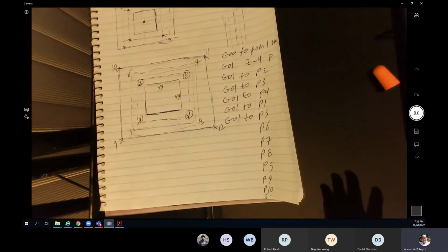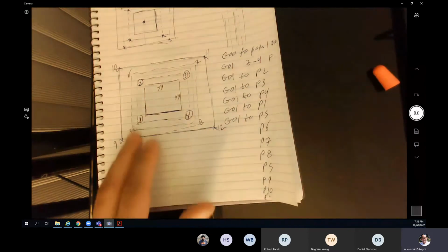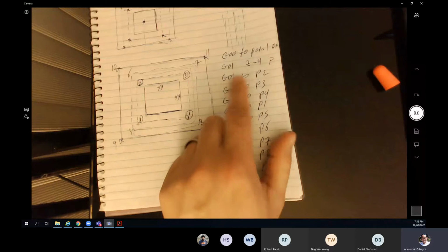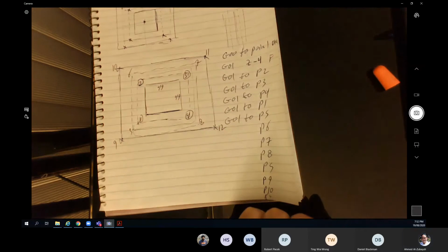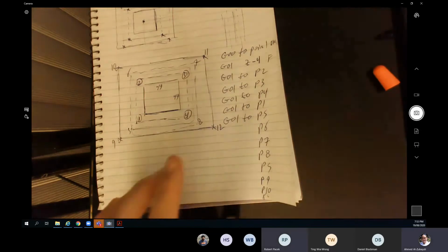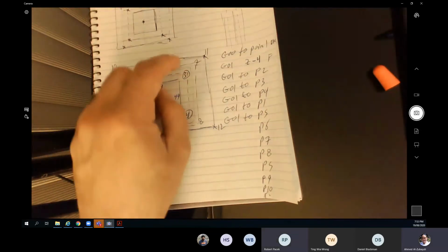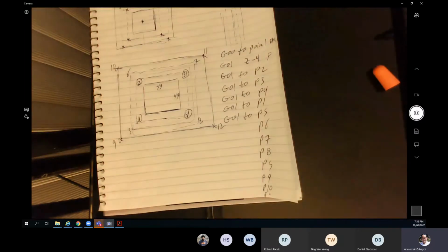Rajith, do you have any question about the code? Now, when I write the points, I consider that you will find the X and Y of each location and put it here, G01, X and Y, X and Y, and so on. And do we need to inspect it as well again? Oh, yeah, of course. No, because we're still under the setup, so don't inspect it now. We still have to do another operation, which is cutting the slot and drilling the holes in the same setup. We didn't remove the part from the machine yet. You don't have to take it out and inspect it each time.